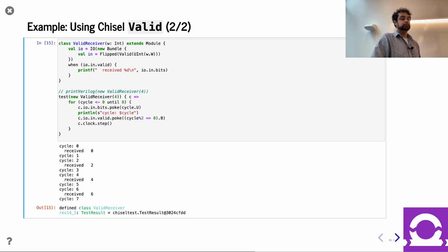Hmm. Yeah, so if you're using whens to assign an output to something, and there's a path through the whens that leaves the thing unspecified, it will error. It'll tell you that this thing has an unspecified condition. So you have whens, and you can have otherwise. Alternatively, you can use the last connect semantics and give a default value, like x connected to 2, and sometimes overwrite it with the when.